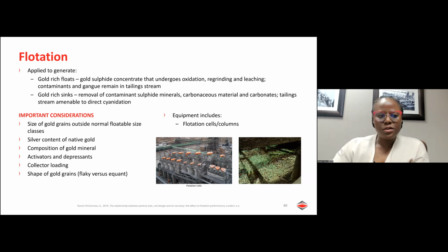So the important considerations include the size of the gold grains, the composition of your stream, and the selection of your activators and depressants that are used in your flotation circuit. The types of equipment that are generally used are your agitation tanks and your flotation columns.